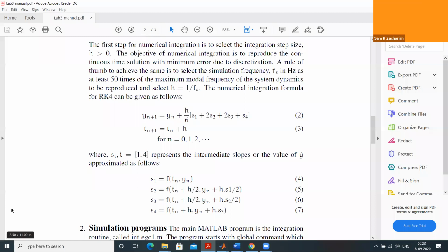Another is the frequency associated with a digital control system or sampled data control system. The sampling frequency for control is even higher. It is not simply conserving the message. We have to ensure that the sampling process will not introduce unnecessary phase lag in the system, and hence that requirement is even higher.